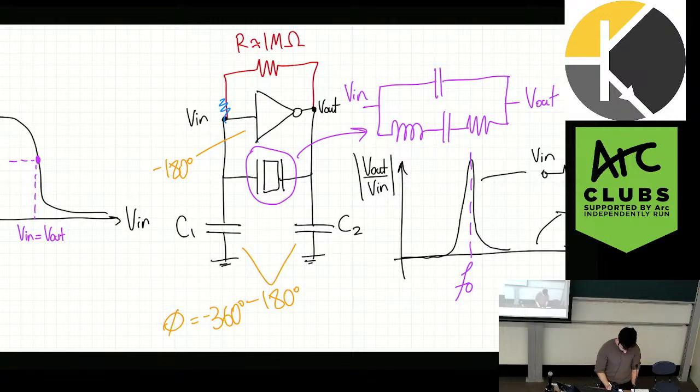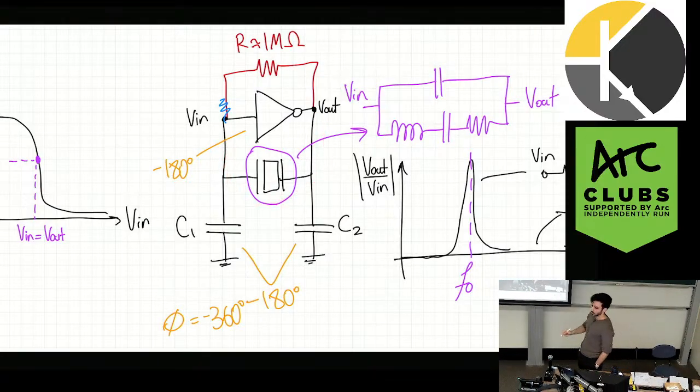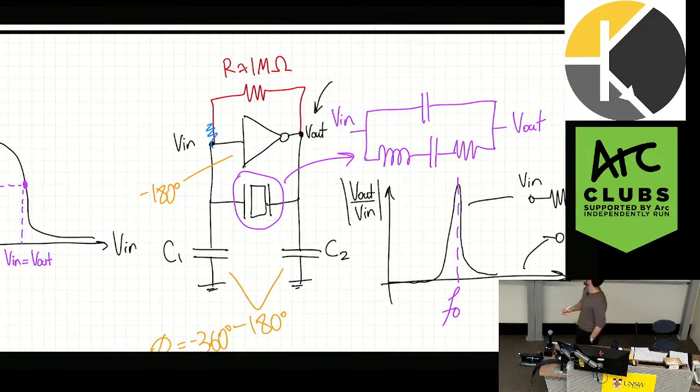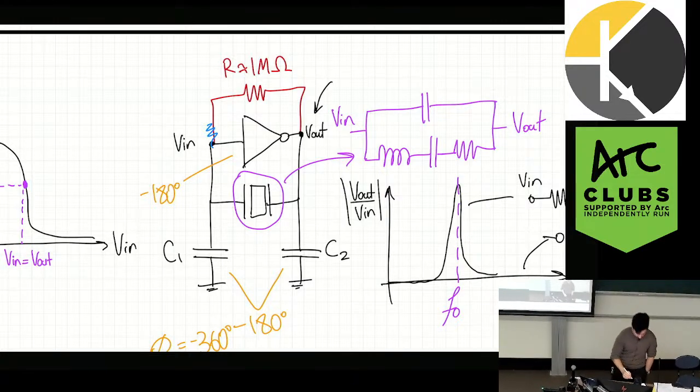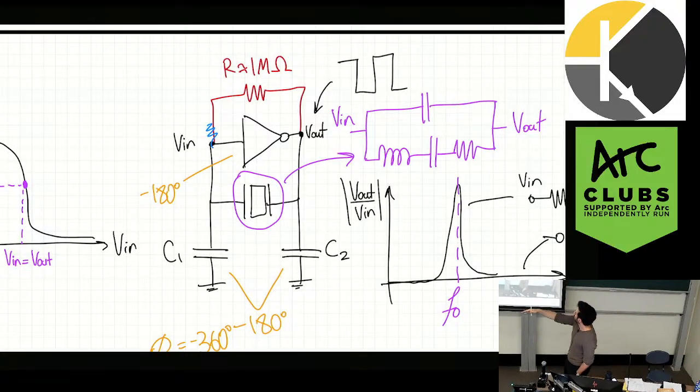So you have an input that essentially starts up, so we default it at the middle of that transfer characteristic. So a little noise flicks it on. Then that signal essentially gets saturated, and then it goes through the feedback loop, right? And it experiences a negative 360 degree phase shift. But not only that, right? So we can imagine what's happening at the output here. It's getting a little messy. But because it's the output of an inverter, we know it's flicking back and forth, right? Let's just assume it's flicked back and forth, right? Now, when this goes through that filter, what happens?